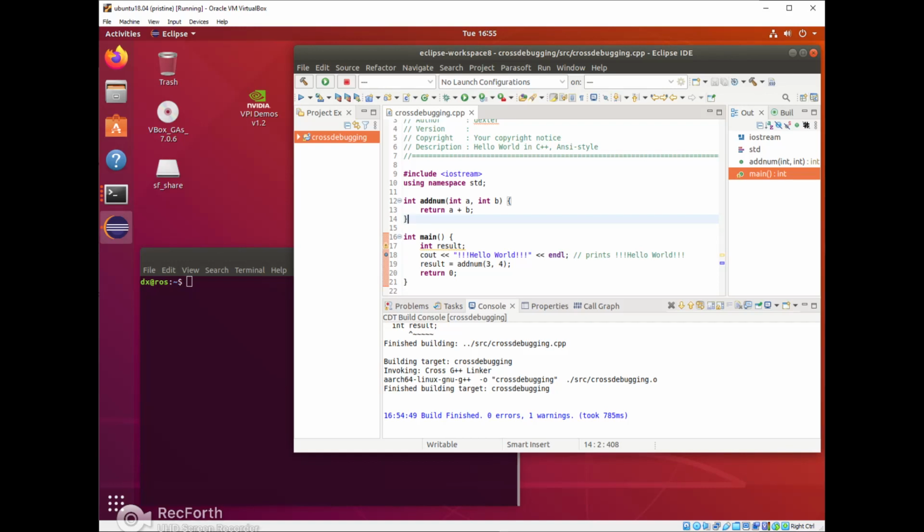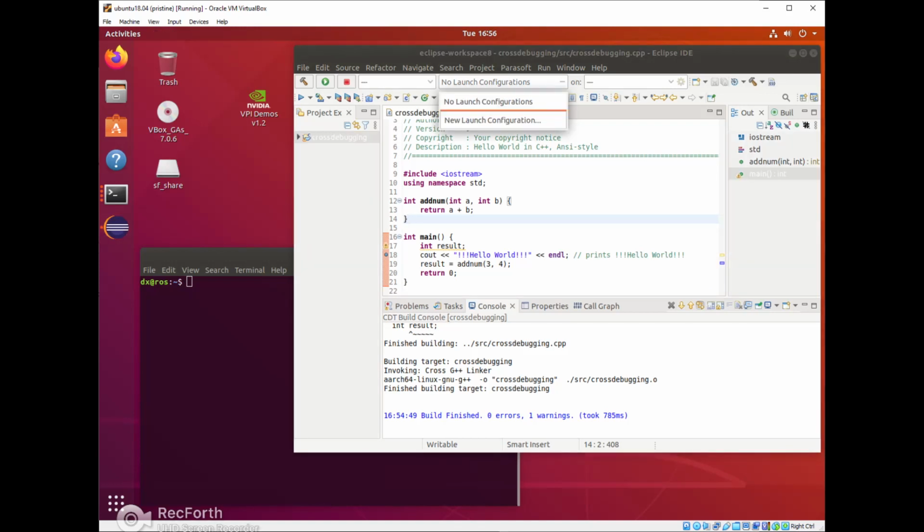But in my other video, when I use GDB, you will see there that I am the one who manually copied the binary there. And then I manually run the GDB server in the remote board. So again, if you watch that video, you will see the fundamental basics of the flow. But since we're using the Eclipse IDE here, the IDE is going to be the one doing that for us. But we need to tell the IDE the IP address of the remote board.